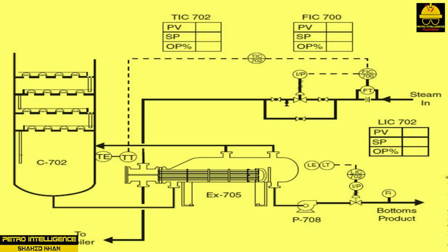Bottom system. Temperatures in the bottom of C702 are controlled at 222 degrees Fahrenheit. A kettle reboiler, X705, utilizes a natural circulation feed system as shown in the picture. Gravity flow provides a constant level to the reboiler, where levels are held at 50% by LIC702. This level allows the upper 2 tubes in the reboiler to be exposed above the liquid level to ensure good vapor return to the column. LIC702 allows the 92% hot pentane to flow to X702 and then to TK730 in the tank farm. Bottom flow rates are around 126 GPM.